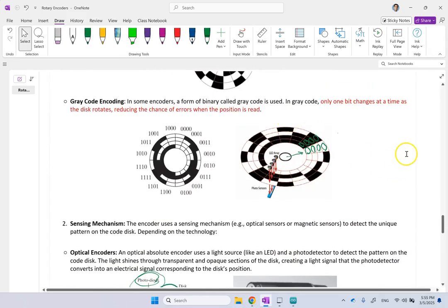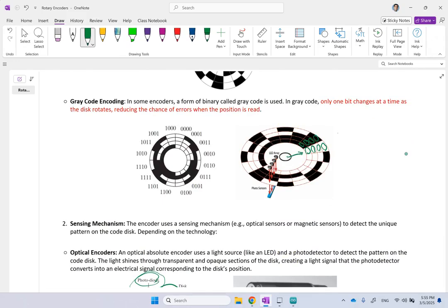How come? Well, look here. In this radial direction, as I said, instead of one of these slots, you have four of them. In this direction, you have three and one opaque, or one closed. In this direction, you only have two, then one closed, then one hole again, and so on. And because you have four of these, this is like a 4-bit combination.